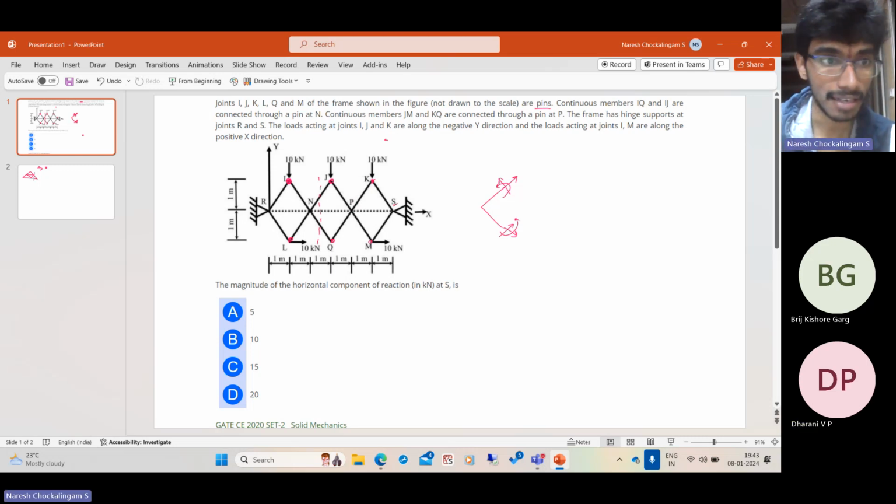Yeah. But I guess where you would have got that is I checked the solution on the GATE portal. One of the students, yeah, so that is extremely incorrect. I should say it is incorrect. I remember what he has done is he made a cut here and then exposed the unknowns here, and he assumed that the forces are axial. But the problem is this is a frame. This is not a truss. And if it is a truss, this is unstable. So that is incorrect.